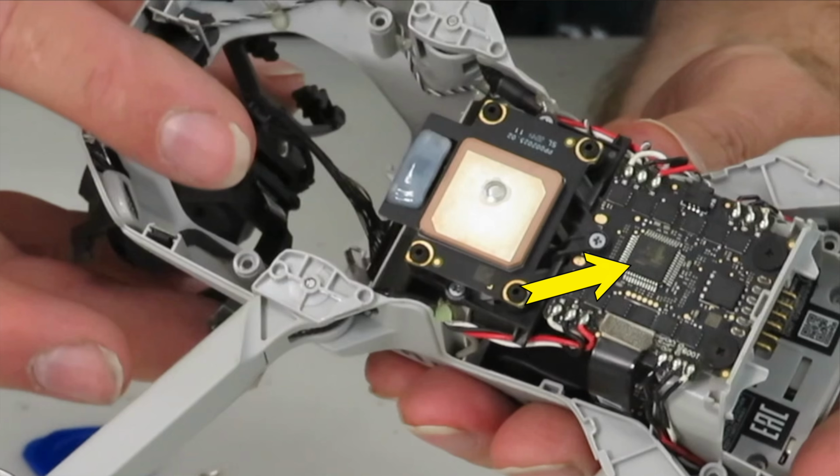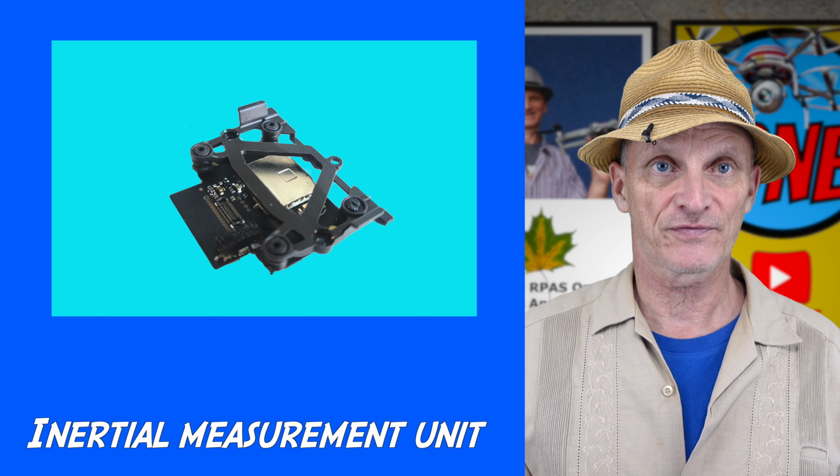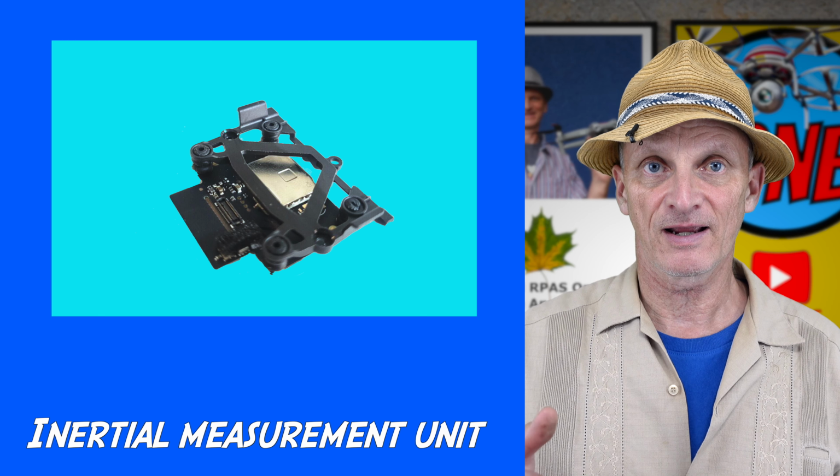Helping all this work together is the IMU, Inertial Measurement Unit. It combines multiple sensors and gives the control module accurate data about orientation and movement. Calibration of the compass and IMU is critical, and you should log these calibrations as part of your maintenance records.